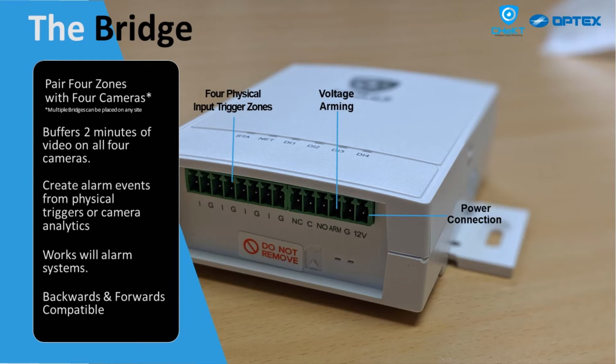All 4 channels of the bridge, what we're doing on the unit once we've authenticated to a camera is we're buffering the video. So we're buffering all 4 channels. And so the pre-alarm and post-alarm information of a physical trigger or analytics is created off of that memory of our device. So that's how we create this consistent pre-alarm event information for the monitoring center. And that's very important to understand, because with monitoring centers, operators need to see what happened moments before that alarm event took place and moments after. And so with that buffering of 2 minutes of video for each channel, we can create that experience for operators.